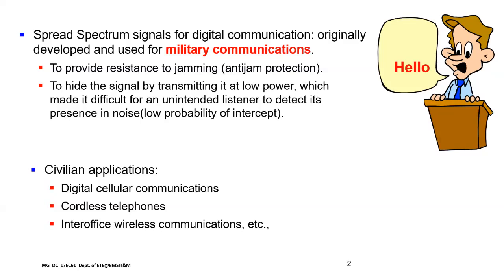That is the first characteristic. The second one is that the information bearing signal is spread by using a code called pseudo noise code, which is random in nature. This spread signal appears random to receivers other than the intended receivers. In that way it provides more secure communication.